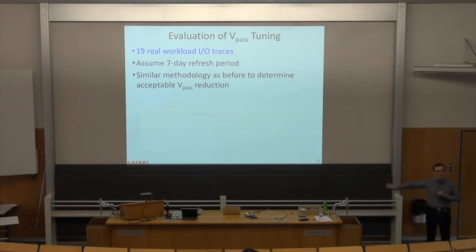You don't want to use costly ECC to correct for errors that you can otherwise correct with simpler mechanisms like refresh. And a 7-day refresh is not bad, assuming you're powered up, of course. Maybe every 14 days is even better. If you remember last lecture, if you go to every day, now your overheads become increasing. But if you refresh every 7 days, it's not bad.